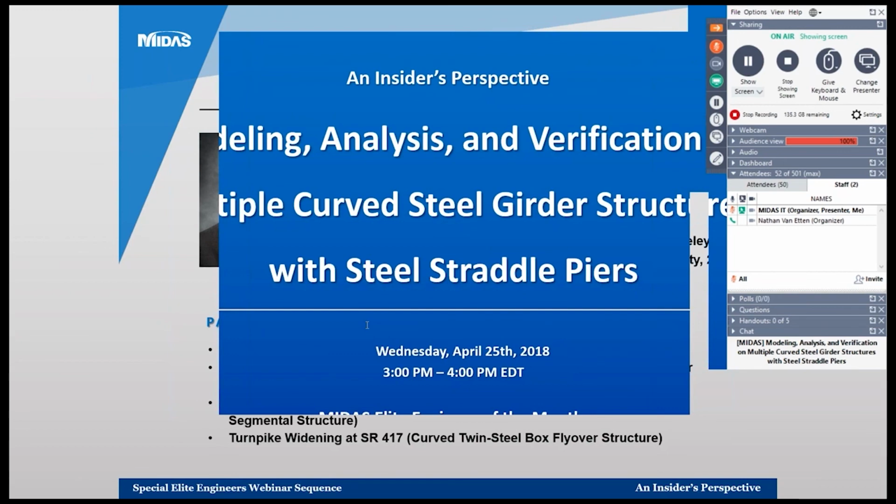With regards to the deck sequence, I highly believe it's very important to always model the correct deck pouring sequence. As the deck pouring sequence occurs, there's a buildup of shears and moments, and this is discussed a lot in the NSBA handbooks. Because of that, all those different loads, all those locked-in forces, all the changes of behaviors will create different springs. So make sure that you always apply a deck pouring sequence when using a program like MIDAS Civil.